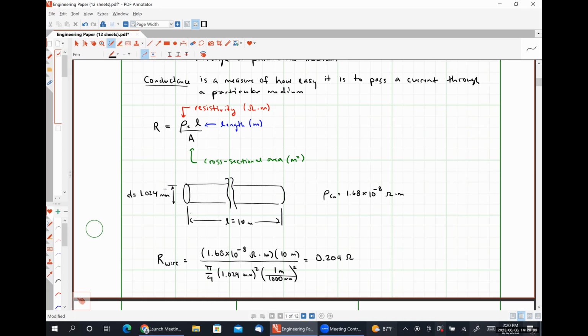What was the smallest resistor that you guys used in your previous classes? Anybody remember? 5 ohms? No, that doesn't sound right. Was it 220? So in the Engineering 120 series, to make your LEDs shine the brightest without burning them out, you would usually put either a 220 ohm resistor or a 470 ohm resistor in series with your LED.